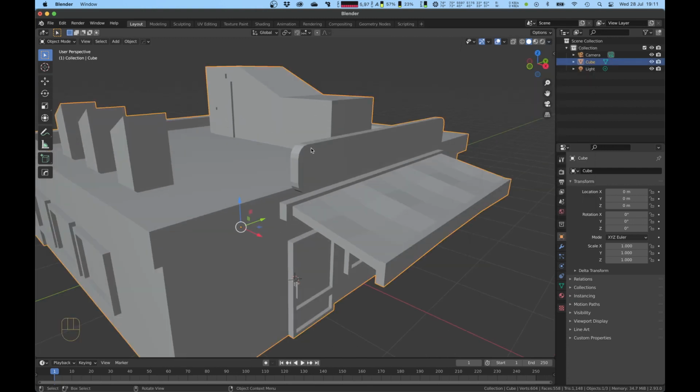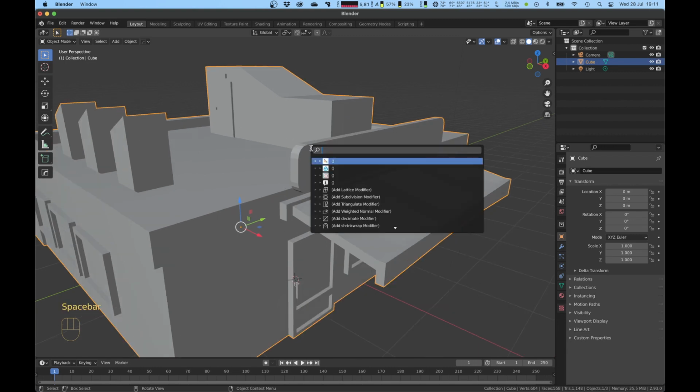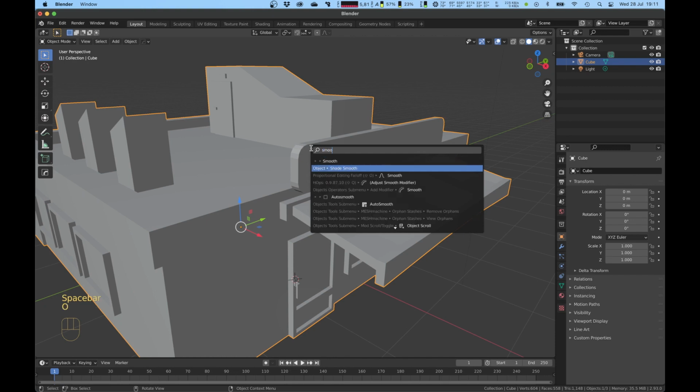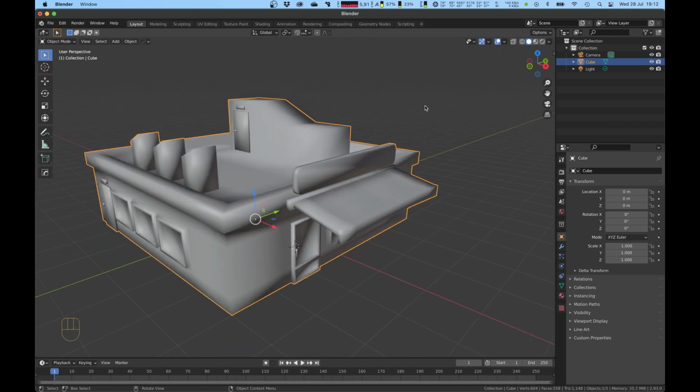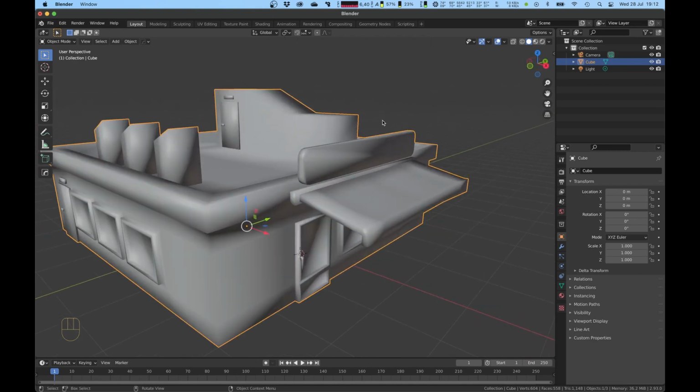And to do that, I will show you Blender's search operator. If you hit F3, you have this search opening up and this allows you to find a lot of Blender operations. I've personally remapped F3 to space because that's easier for me on my laptop. Now search for smooth and choose Object, Shade, Smooth. Now everything became worse. But don't worry, smoothing works by flattening the angles between adjacent faces without changing or adding geometry. It's purely visual and adds an organic look.